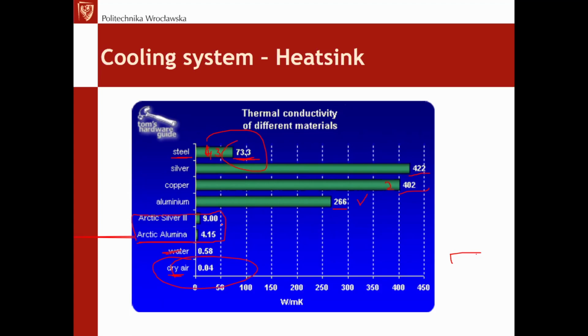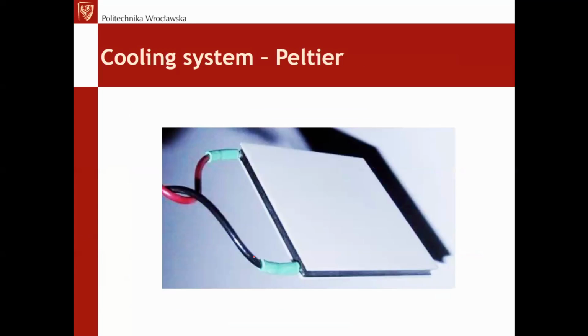But of course, we need only a thin layer. On the other side, don't forget about using them only on thin layers. Never use them on layers of 1 millimeter, 2, 5, or 10, because they are much weaker thermal conductors than aluminum, copper, and even steel. So that's important. We have to avoid the problem with air between the heat sinks, and use thermal conductive paste instead.